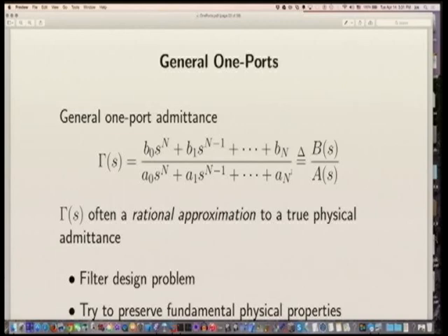And if there are no dashpots, then it'll be lossless. That means all the poles will be exactly on the j omega axis. And the zeros will have special properties that I'll tell you shortly. But if we have dashpots, then there'll be damping, and that'll pull the poles away from the j omega axis. And we'll have a more typical system. It'll die out when you hit it.